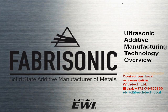Right now you can see the ultrasonic additive manufacturing process in action. Thin layers of metal are rolled underneath of a welding sonotrode. The sonotrode vibrates back and forth and creates a solid-state ultrasonic bond. We repeat this process left to right, adding material as we go to build up a three-dimensional part.